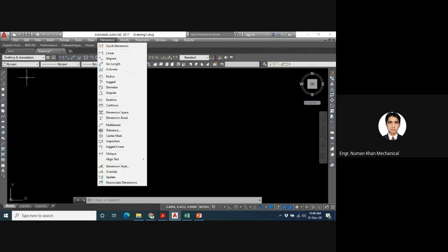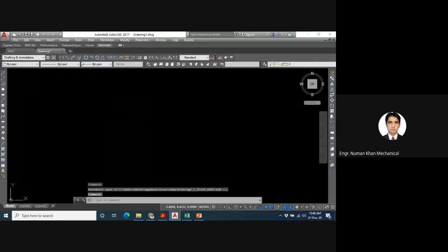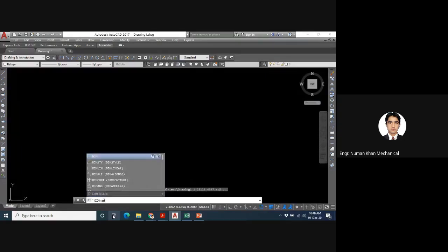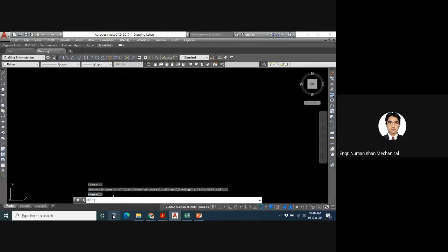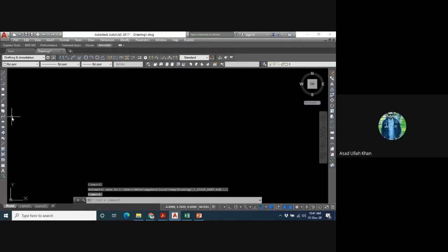और अगर आप यहाँ से नहीं टूल बार से, तो यू मस्ट हैव द डायमेंशन टूल बार, उधर से आप सेलेक्ट कर सकते हो. अगर आप की से करना चाहते हो तो फिर हर एक के लिए डिम अलाइन, डिम एंगुलर, डिम रेडियस, डिम डाया, इस तरह के कुछ कमांड आपको एंटर करने पड़ेंगे, फिर वो काम हो जाएगा. लेट्स से डिम अलाइन, ये अलाइन डायमेंशन सेलेक्ट करेगा. डिम डाया, ये डायमीटर सेलेक्ट करेगा. डिम रेडियस, ये रेडियस सेलेक्ट करेगा, ठीक है. तो डिम पहले डाल के फिर उसके 3 डिजिट डाल के वो आ जाएगा. ओके सर, ओके.